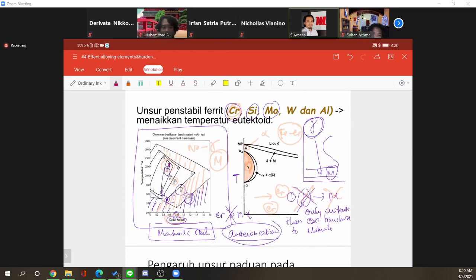But the answer, in short, is that they do not totally cancel out each other, but they sum up and become an equivalent, because there is interaction between these parameters. So there will be chromium equivalent and nickel equivalent. That is what we will use as a guide.